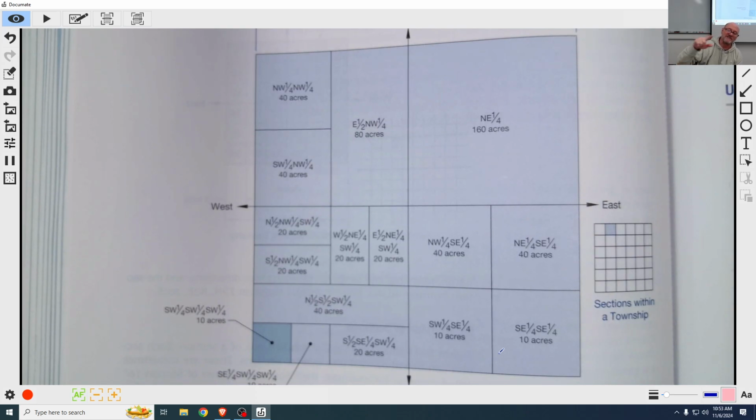And a township is 6 by 6 sections, right? So 36 square miles-ish, because a section is 1 mile by 1 mile square. And as far as acres go, by definition 1 square mile is equal to 640 acres, right? Okay. And then broken up, here's the first fourth. This is a quarter. This would be called a quarter section. And that's the northeast quarter of that section, right?